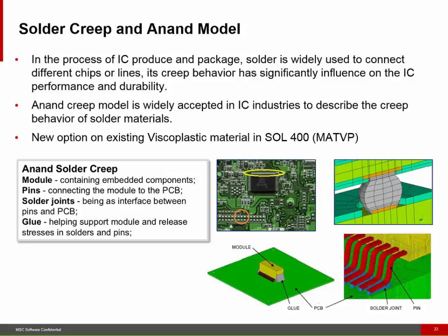So the Anand creep model is widely used and accepted in this industry to simulate the performance and the behavior of solder material. So we've added the Anand creep model as a new option on the existing MATVP, so the viscoplastic material in solution 400.